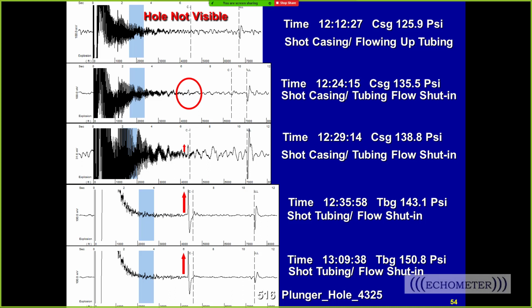All right. One more question from Manuel says, what is the approximate percentage of liquid fallback in an annular flow profile in a gas condensate well? Okay, well, there's a rule of thumb. If you are liquid loaded and you try to vent the well, then the rule of thumb is 7% of the liquid falls back per 1,000 foot of depth. So let's say you have a well that's 10,000 foot deep.